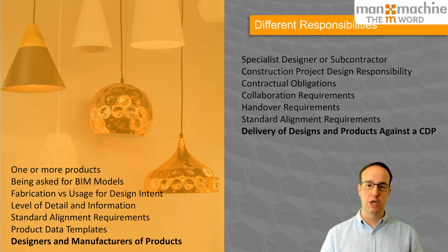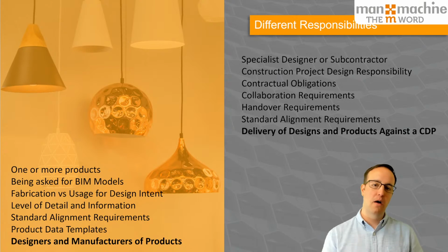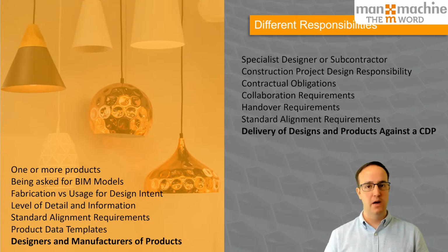There's going to be a BIM execution plan against an exchange information requirements. There's going to be some asset information requirements. And as a manufacturer who both designs the product and then places it in the building and designs around it for that specific purpose, you're going to need to read, digest and understand those and the whole ISO 19650 workflow to make sure that you are delivering what you're signing up for at the end of the day.